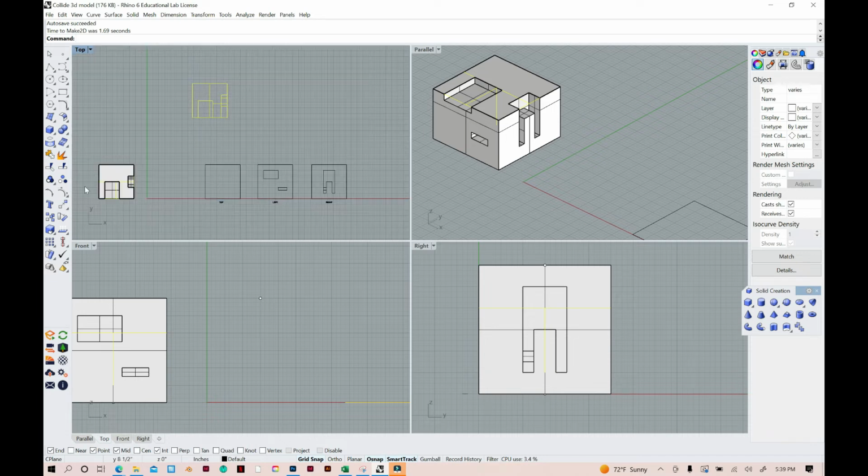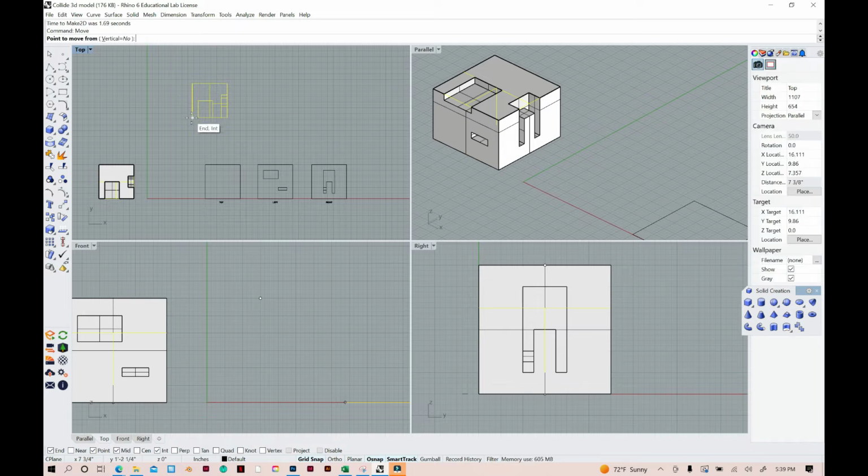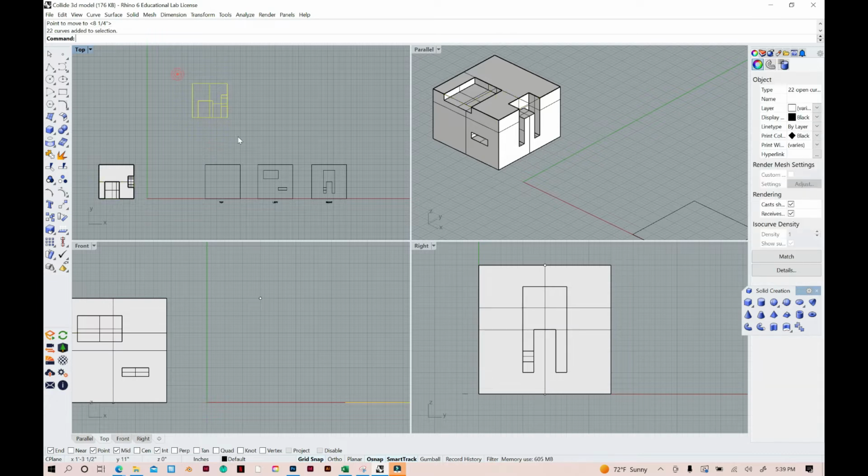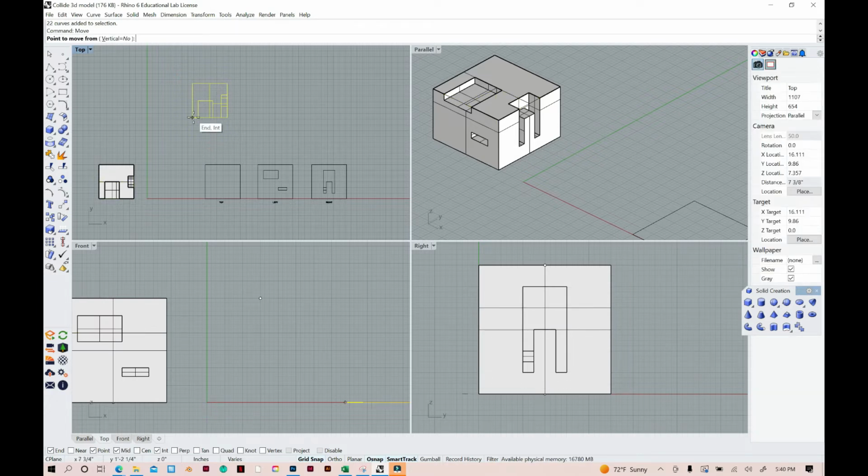So it appeared here, so I didn't have to move it over, but I will keep it there just for myself. So what you might notice is that your clipping plane also got selected. So to quickly fix this, press Escape before you click anything, and then go back and just highlight your plan and then move that. So the clipping plane is no longer selected.